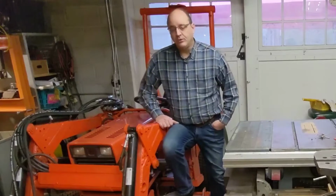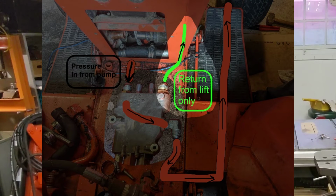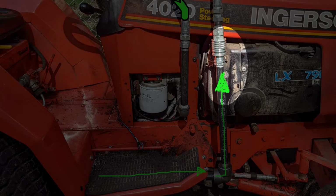In this new design, there will still be 3 lines attached to the travel control valve. It will still have the high pressure feed line coming from the pump. It'll have a new low pressure line leaving from the standard return to tank port. And it'll have a new high pressure feed line leaving the new power beyond port. That new line will head outboard underneath the right side footrest. At rest position, the high pressure oil entering the travel control valve will all pass through and exit via the new power beyond port, where it will make its way underneath the right hand footrest and ultimately arrive at a quick disconnect in front of the right hand footrest.